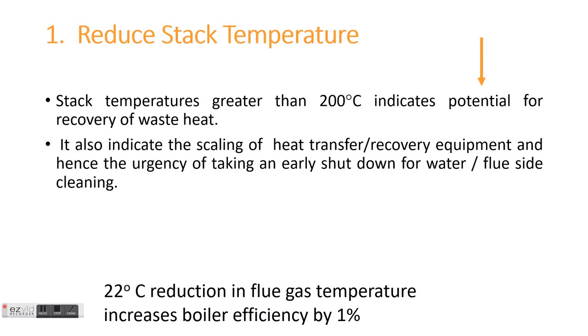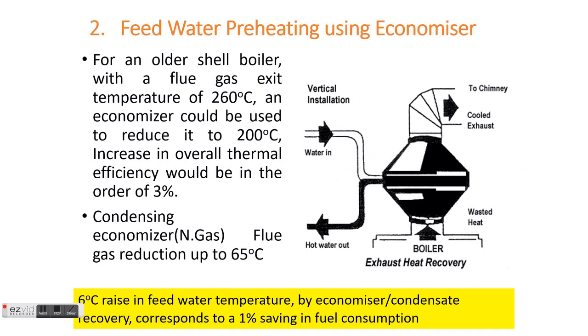However, it should not be so low that water vapor in the exhaust condenses on the stack walls. This is important in fuels containing significant sulfur, as low temperature can lead to sulfur dew point corrosion. Stack temperatures greater than 200 degrees Celsius indicate potential for recovery of waste heat. It also indicates the scaling of heat transfer recovery equipment, and hence the urgency of taking an early shutdown for water side and flue side cleaning.